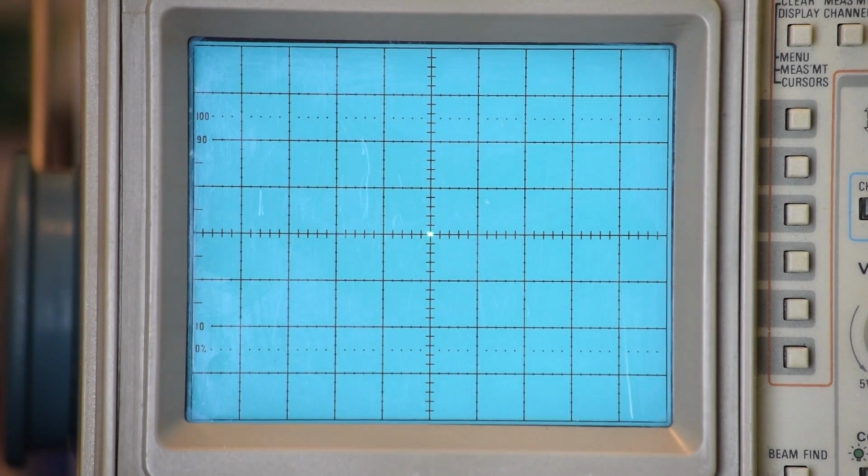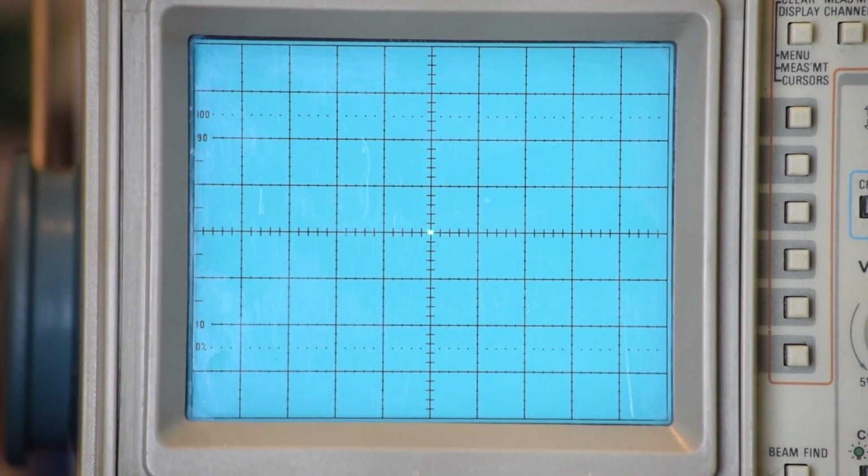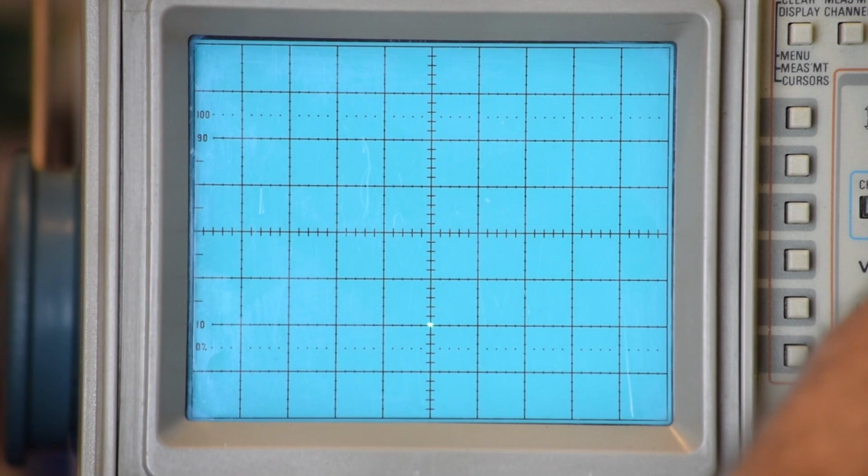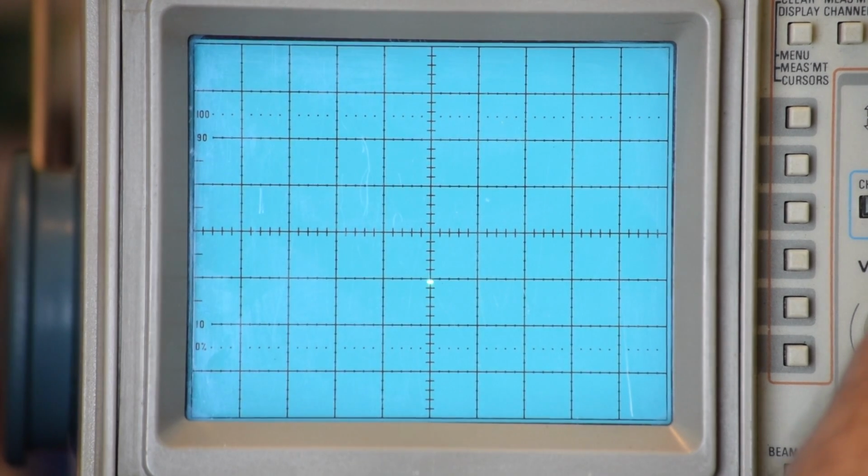Then we'll take the Y pot address and go to the negative reference, and that's pretty far off, so let's see if I can adjust that with calibration. Well, what I did is I just took the calibrated or variable portion of the second channel, which is controlling the Y, out of the cal detent, and that only goes up from there. So I have to increase the vertical sensitivity effectively. So now I can actually bring that to the point at the bottom of the scope there.